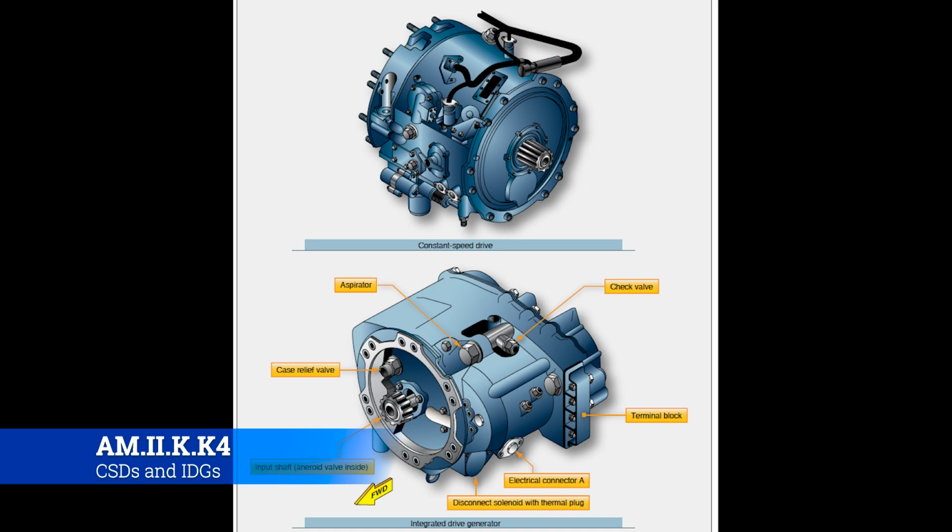Like if it's showing you that you have low fuel or something like that. It's actually just the quality of power that is being generated. So the constant speed drive, or CSD, is used to ensure the alternator rotates at a correct speed to ensure a 400 hertz frequency.